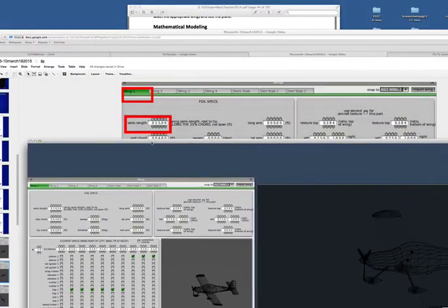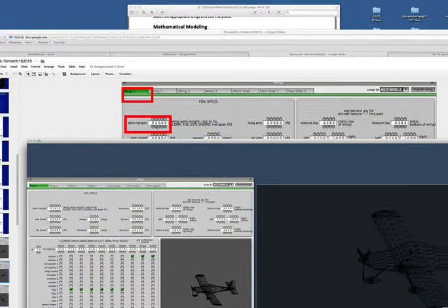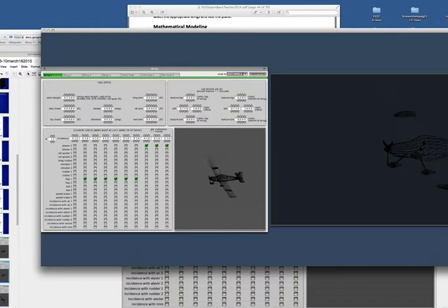Well, on the first wing, we're going to set that semi-length to 25. So I'm going to go right here, and I just go up with the little upper pointers. There it is. See how it stretches out beyond the wingtips?